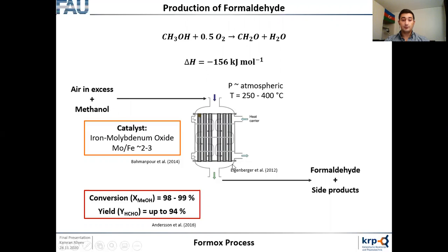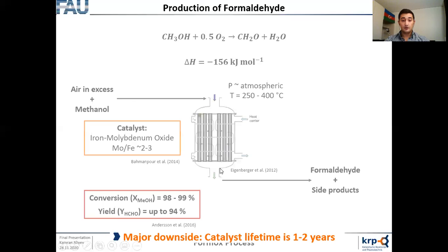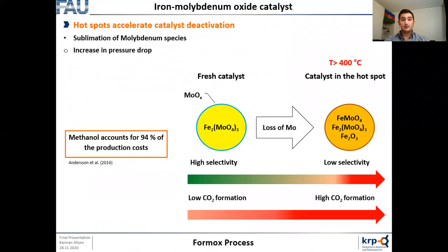In fact, the performance of the catalyst is quite good, and conversion is reaching up to 99%, and yield is reaching up to 94%. However, the major downside of this process is the short catalyst lifetime, which is associated with the deactivation of the catalyst. And catalyst deactivation is actually induced and accelerated by the hotspots, which are typically emerging in the fixed bed reactors, particularly in the case of highly exothermic reactions like in my system.